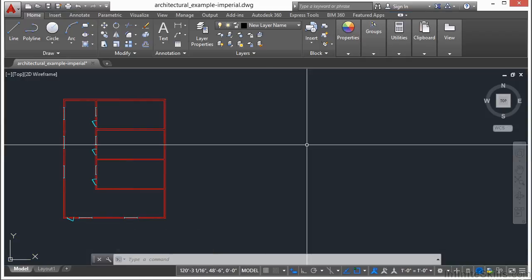The nice thing about being able to do that is that I can have one set of line work, one model, but I may need to display it differently on multiple drawings. Well, this allows me to do that without having to draw new layers for specific reasons. I can use the same ones that have the information on it already that I need. I can just choose to not display it by freezing them in that specific viewport. And on the same note, you can also change things like color and line type by viewport only. That way you can make a construction line, a solid line, show up in one drawing, but then make that a hidden line in another drawing without having to change your drawing objects.